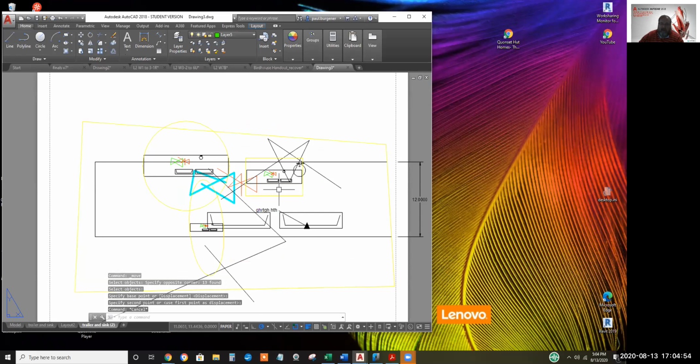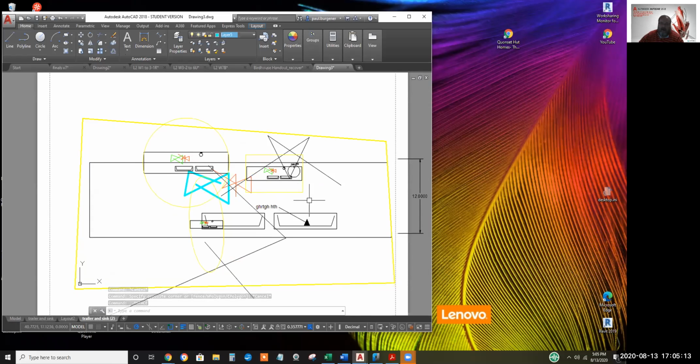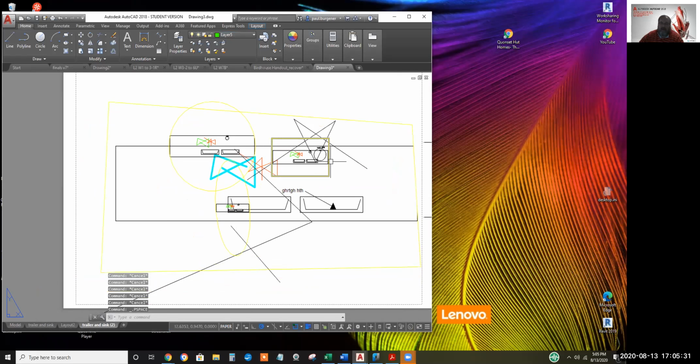Now, how in the world am I going to activate this little one that's totally surrounded by a big one? Watch it make a liar out of me, but I'm going to double click in here and I think it'll activate and deactivate the big one. Yep, activated the big one. So how in the world can I activate the small one within? Well, one way is to temporarily move it outside, but there's another type-in command that allows you to go paper space by clicking the status bar.